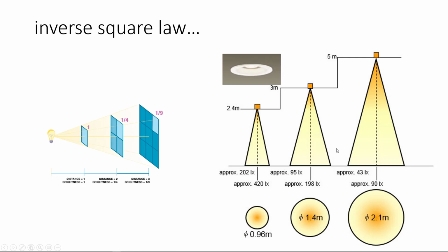So another key concept here for our lighting calculation is the inverse square law, which is to say that the farther away you get, the brightness that is landing on a surface decreases. It's exponential. It's 2 squared: if you double the distance, it's 1/4 the strength. So how does that translate into architectural settings? Well, if you double your ceiling height, you will have 1/4 the quantity of light landing on the floor.